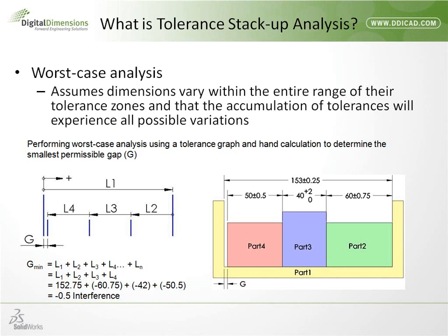Alrighty, so what is tolerance stackup analysis? Of course, it's a worst case analysis. That is, you take your dimensions at their high end and their low end within the range of the tolerance zones and see how they stack up. So here's just one example.